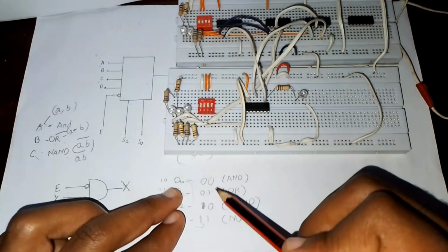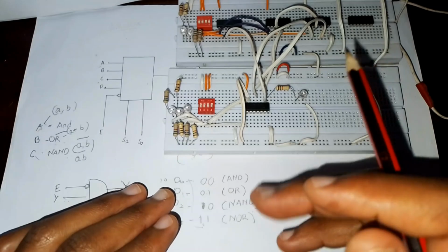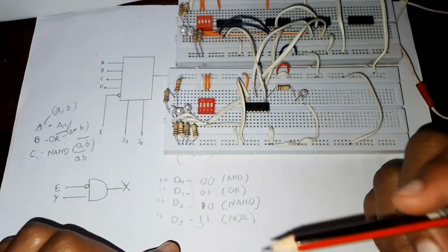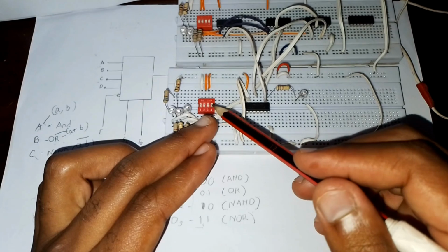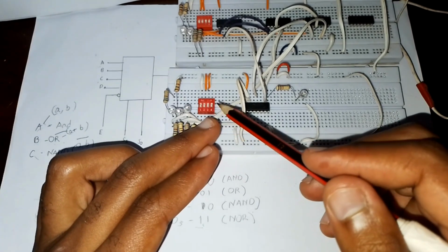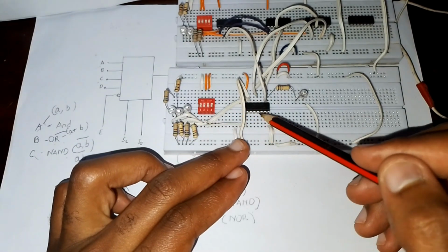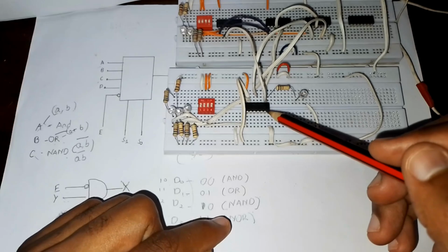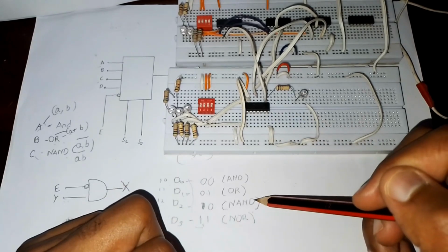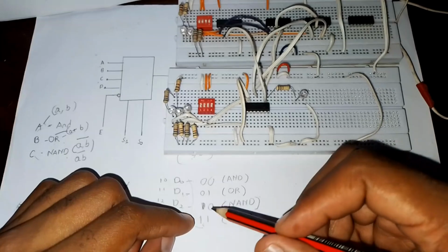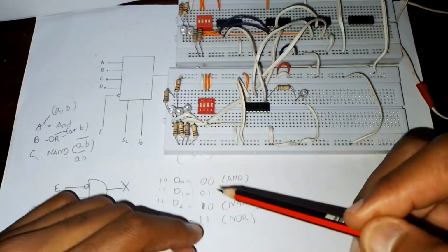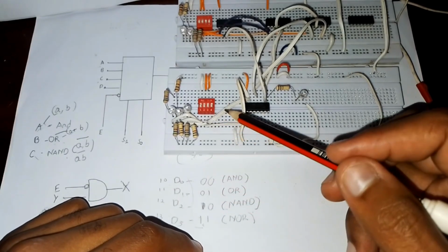So these are the codes that are going to be sourcing out which information that we want to receive. So these codes we feed them to this select line input, then it's going to enter the multiplexer, and the multiplexer is going to choose what you want. Either you want OR, you want NAND, you want NOR, you want AND, whichever, depending on the code that you have placed on the select line.